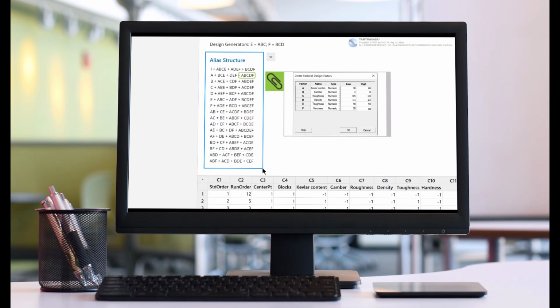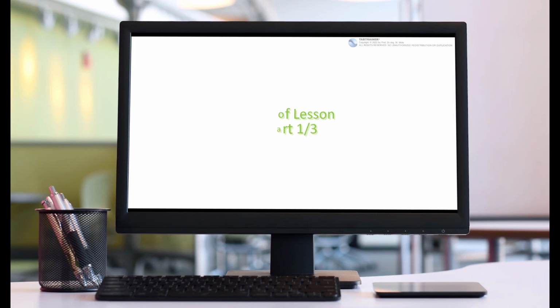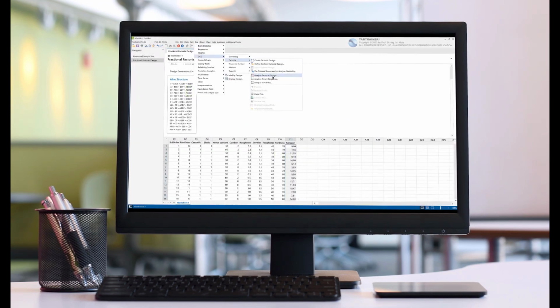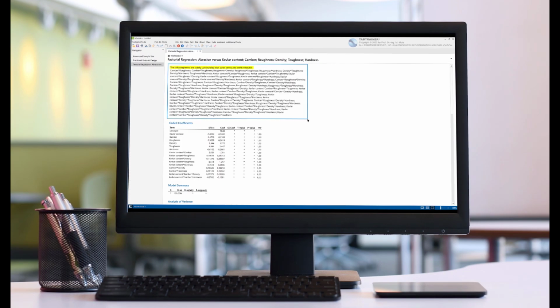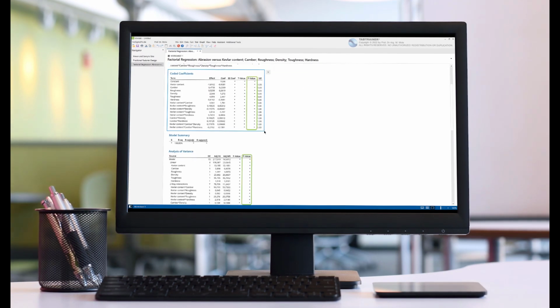At the end of the test period, the material abrasion of the skateboard wheels is determined in grams by calculating the difference between the wheels' weight before and after the wear test. The amount of abrasion in grams is therefore our response variable, which should ideally be as low as possible. This means that the lower the abrasion, the higher the wear resistance of the skateboard wheel, and the higher the